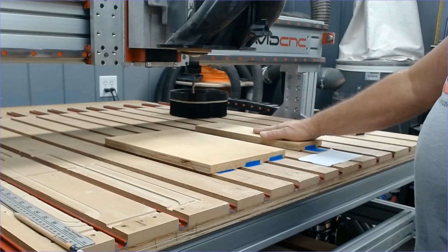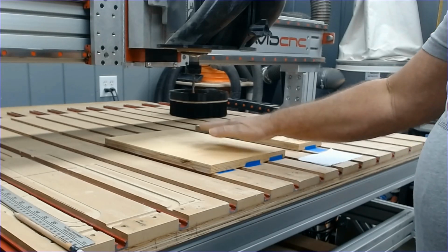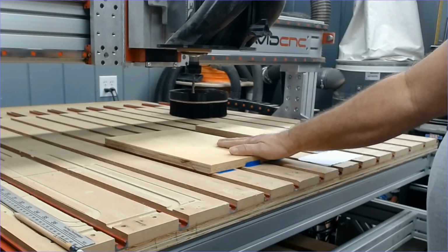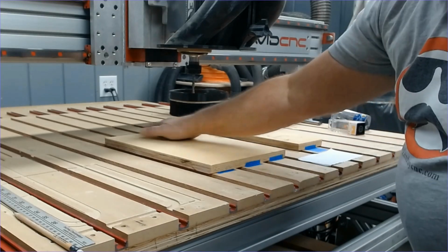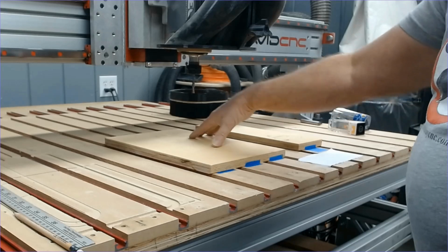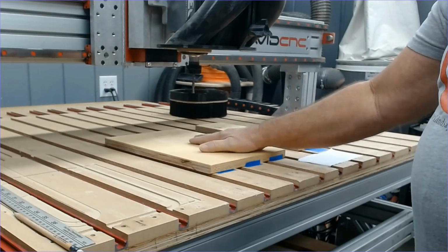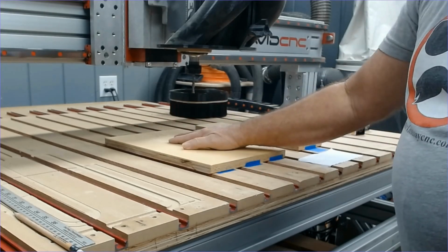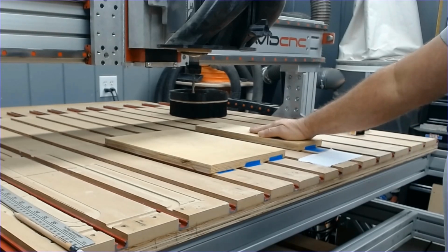This is where this piece comes in, because it doesn't even necessarily have to be the same piece of material. If, for instance, I'm doing a large 3D carve and this entire surface is going to be carved away, after that 3D carve, I don't have anywhere to set my Z0 position to do my profile cutout. That's where this second piece of material comes in.